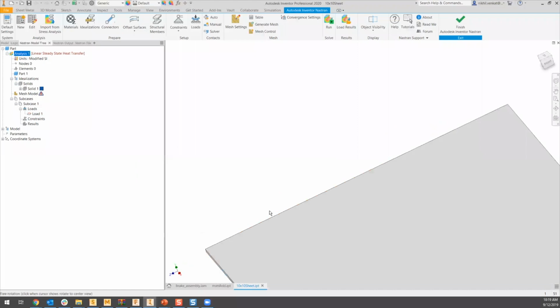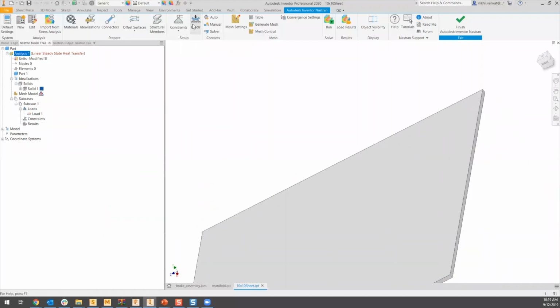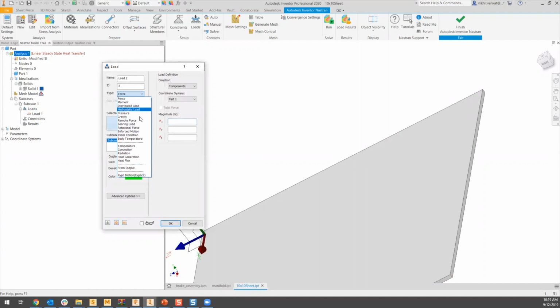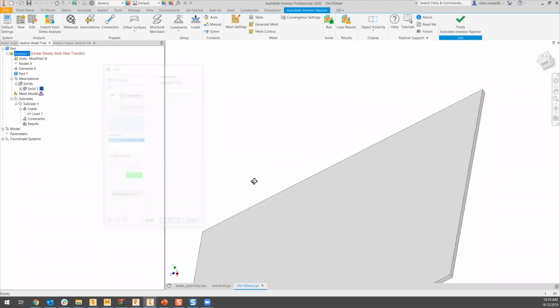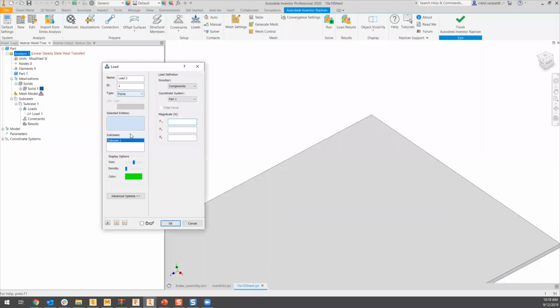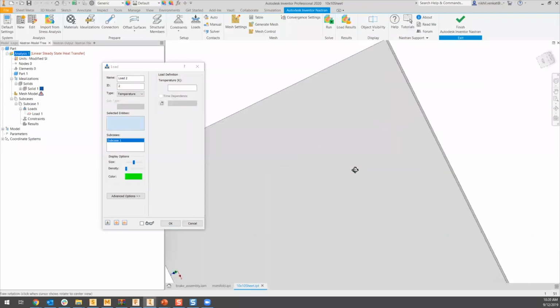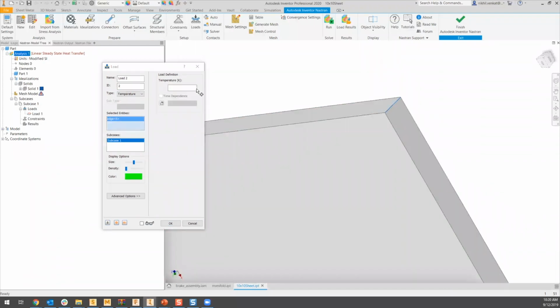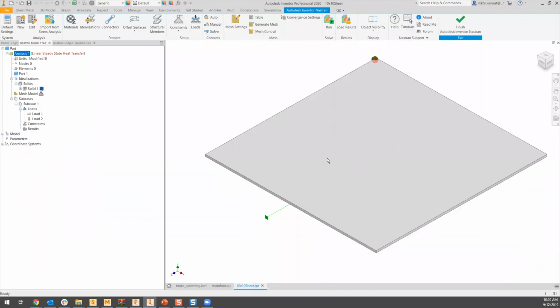Okay. I'll also apply just a direct temperature load. Actually, let's just apply body temperature. Okay. So we will apply a temperature load on just that specific edge of 315 Kelvin. Okay, there you go. That's a glyph for the temperature load. Now we'll go ahead and mesh this.